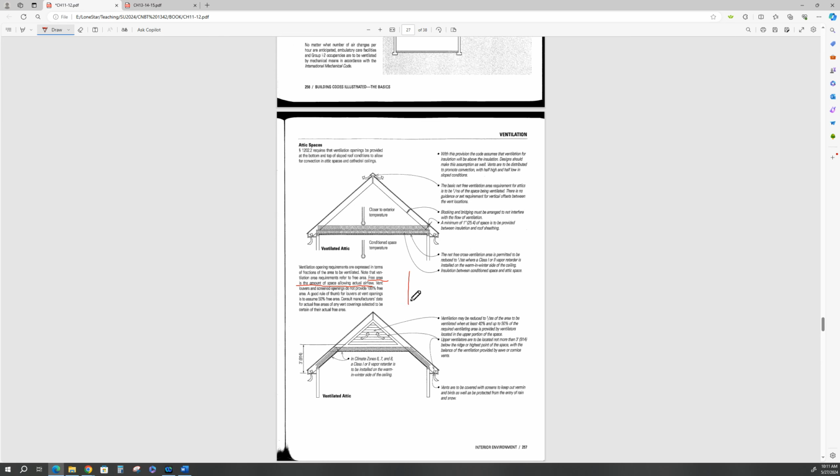In other words, in section, if this is the vent louver, and there are the vents, it keeps the rain out. This whole cross-sectional area, if we're looking at it in sort of an ISO view, and it's a pretty bad drawing, I'm an engineer, I'm not a draftsman, is the amount of area that you can get X CFM through in a natural airflow.